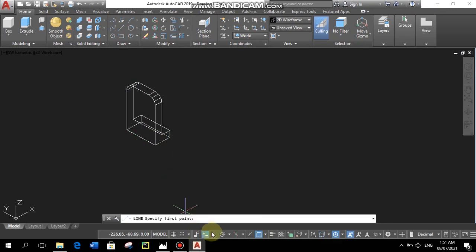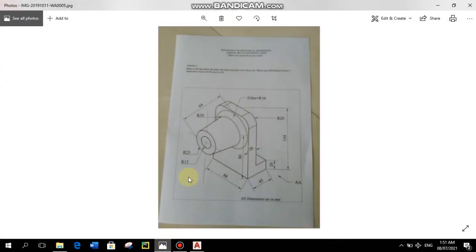This restricts you from drawing lines that are not straight, gives you lines that are at 90 degrees. Take this, it gives you 80, with the line 80, press enter, then you escape to go out of the line command.